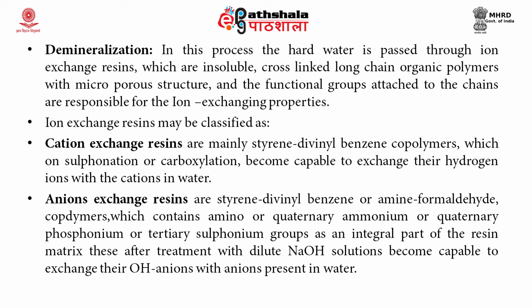Cation exchange resins, as the name suggests, exchange the cations present in the hard water. They are mainly styrene-divinylbenzene copolymers, which after sulfonation or carboxylation are used as cation exchange resins, and they become capable of exchanging their hydrogen ions with the cations present in the hard water.